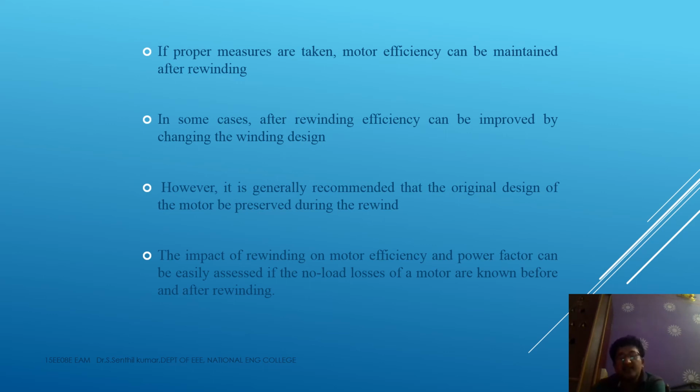In some cases, if we check thoroughly and regularly, the efficiency can be improved after rewinding by changing the winding design. However, in general, it is strongly recommended that the original design of the motors be preserved during rewinding. The impact of rewinding on motor efficiency and power factor can be easily assessed if the no load losses of the motor are known before and after the rewinding.